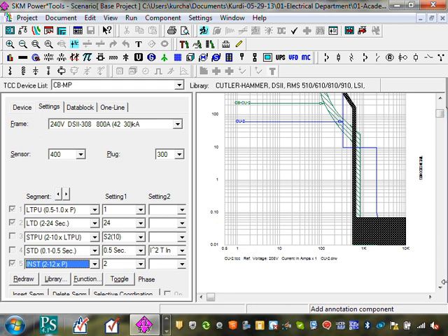So it doesn't matter what happened here. We don't care. We're only looking at this section. They call them instantaneous trip circuit breakers. Who cares? They make cheaper equipment. What they do is use them in conjunction on motors with an overload.